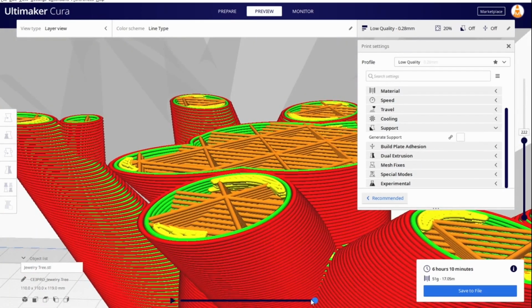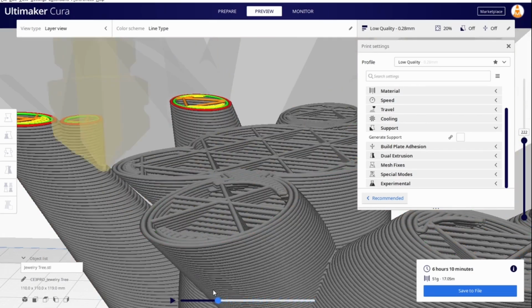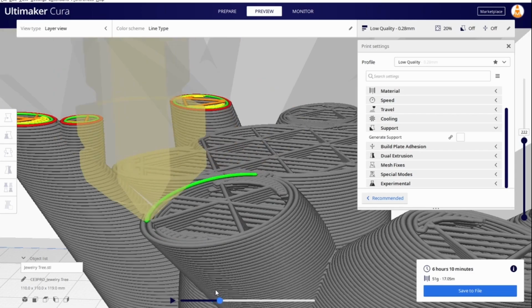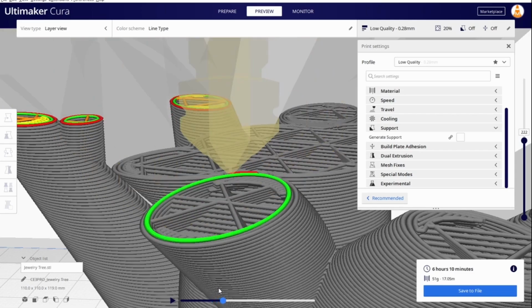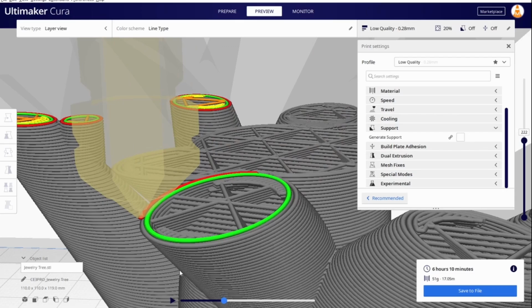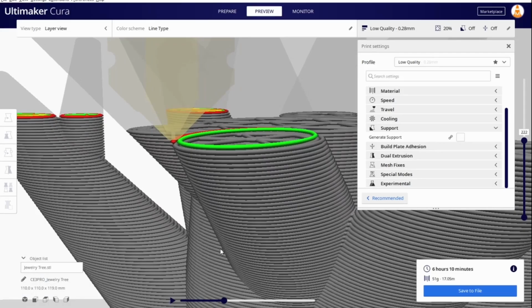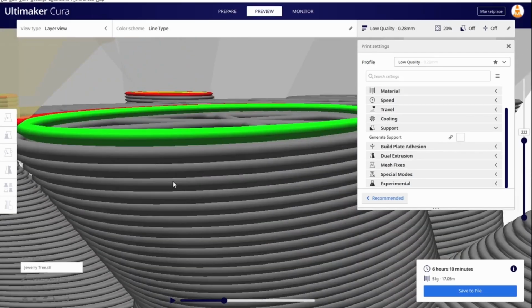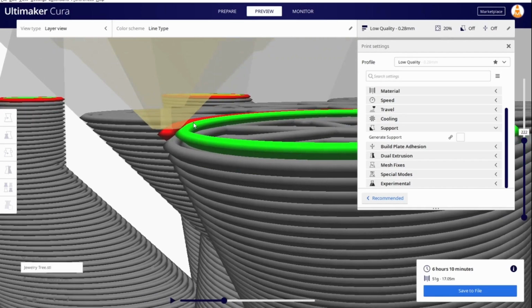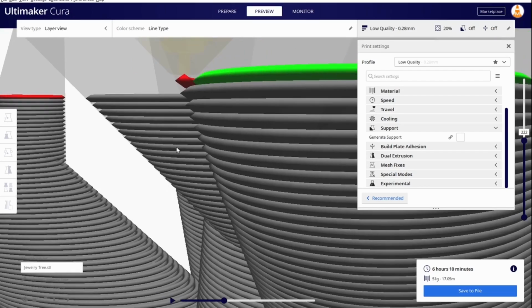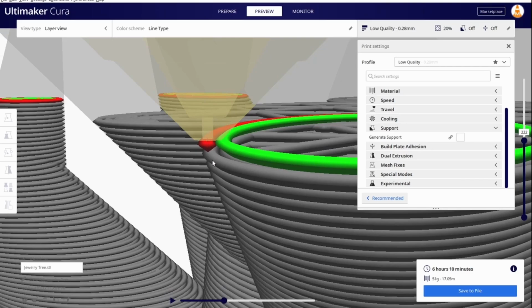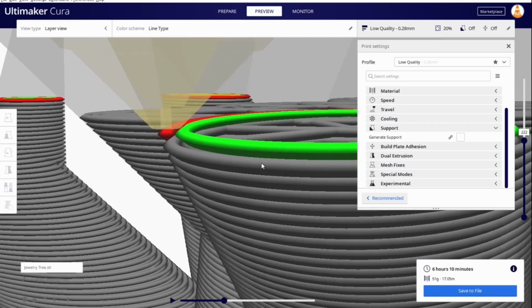I can actually use this to show how our printer is going to draw the layers. It's going to do the inner wall first, and then you can see that as it's putting the outer wall out there, if we zoom in really close, the line that our printer is making, which is the size of the nozzle, a little less than 0.5 millimeter, is halfway over the line below it, which means it should stick well enough to this and not have the ability to really droop over the side.